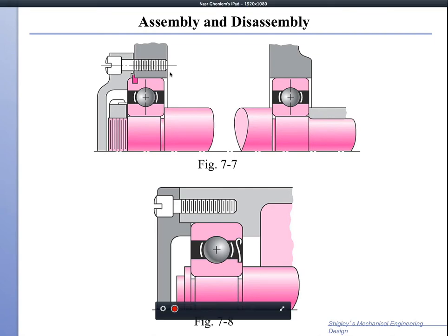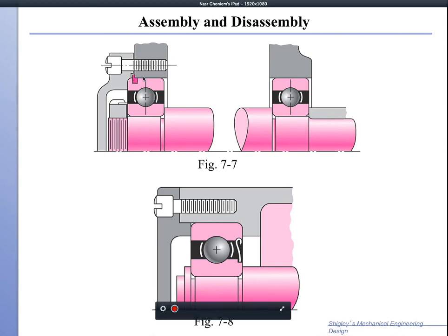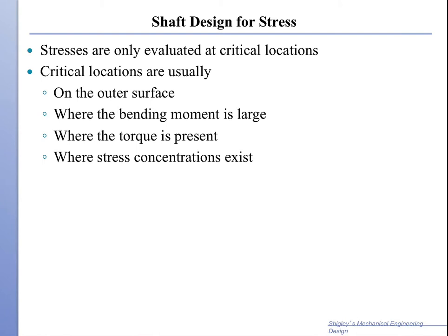When you design the system, you have to design for quick assembly and disassembly. Like you see in this case, there's a little gap here, and the gap is maintained with a spline, so that you can prevent binding, or you can allow for some temperature expansion coefficient to take care of the elongation of the shaft.